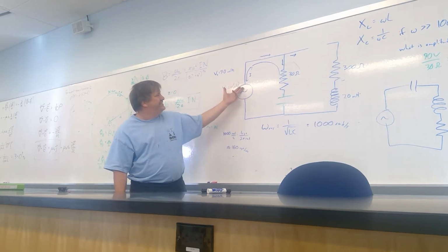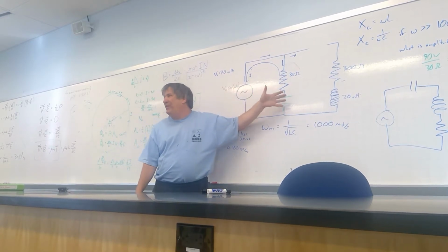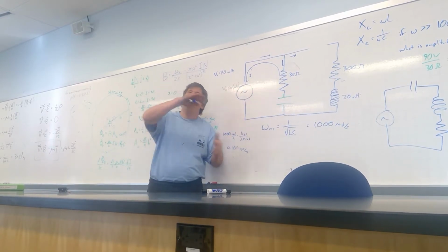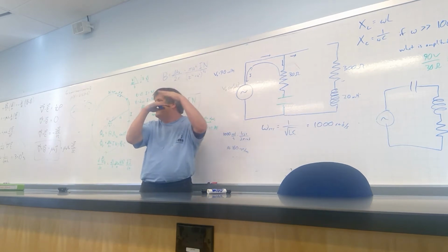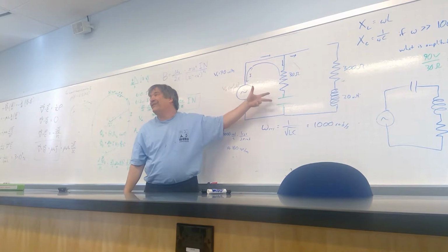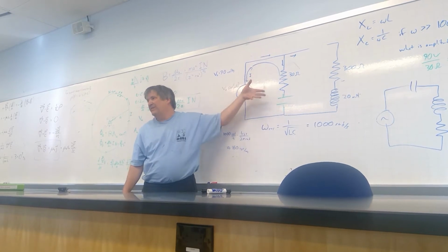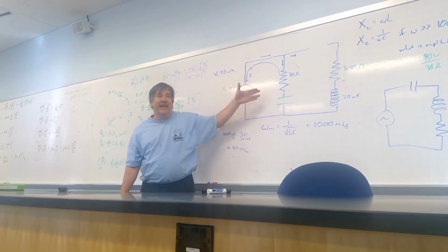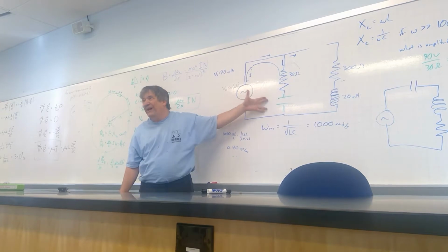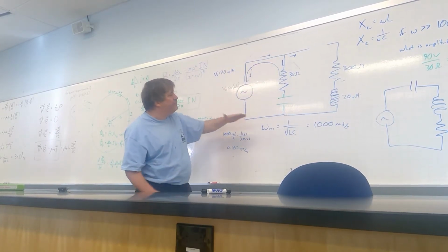Well, if this thing is changing direction once every 3 days or something like that, you pretty much say the capacitor is always at equilibrium. Maybe tomorrow it'll want a different amount of charge on it, but for the most part, I'm not needing to run any current to charge the capacitor. The capacitor is already where it wants to be. In fact, it's not allowing current to flow because any current that flowed through would change its voltage, and it's already got the equilibrium voltage it wants for the moment. So at low frequency, the capacitor acts like a break in the circuit.